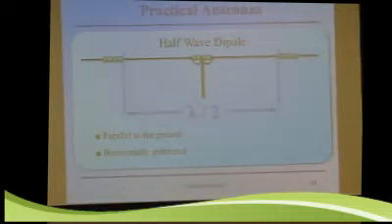Okay, well, here's a half-wave dipole. We've been talking about it, and this is kind of the nuts and bolts of it. Essentially you have a half-wave antenna, two quarter-wave halves split in the middle. Dipole doesn't actually mean the absolute middle, but it means two pieces. It's generally parallel to the ground, so it's horizontally polarized. That's really all you need: a quarter-wave wire here, a quarter-wave wire here, some insulators, then feed line, which may or may not be coax, and that's an antenna.